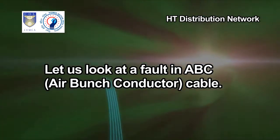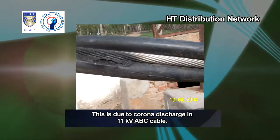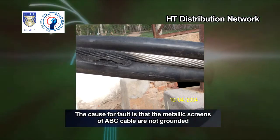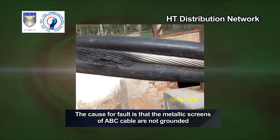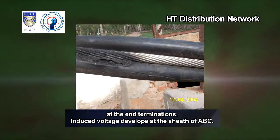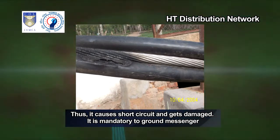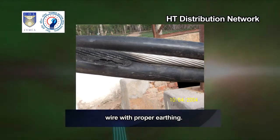Let us look at a fault in ABC, air bunch conductor cable. This is due to corona discharge in 11 kV ABC cable. The cause of the fault is that the metallic screens of the ABC cable are not grounded at the end terminations. Induced voltage develops at the sheath of the ABC. Thus, it causes a short circuit and gets damaged. It is mandatory to ground the messenger wire with proper earthing.